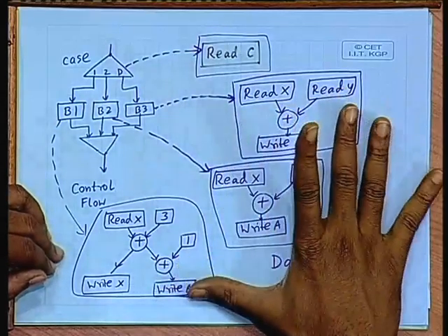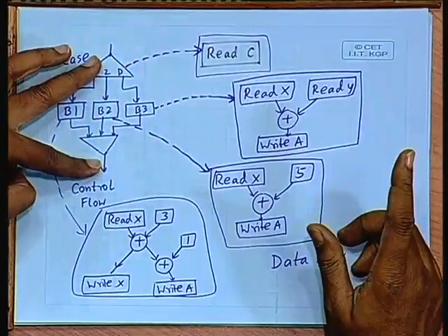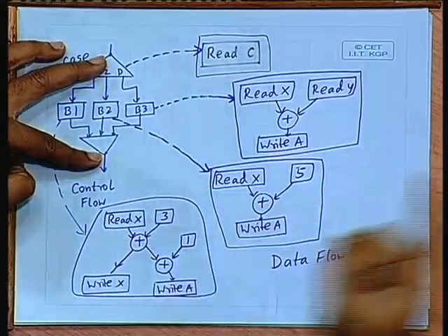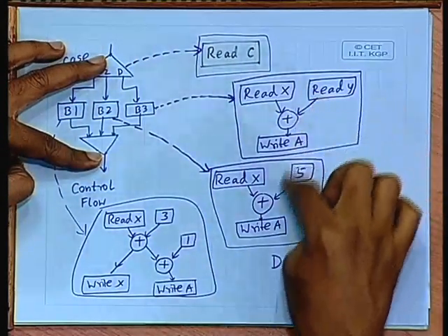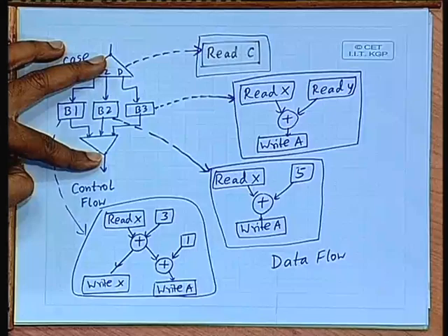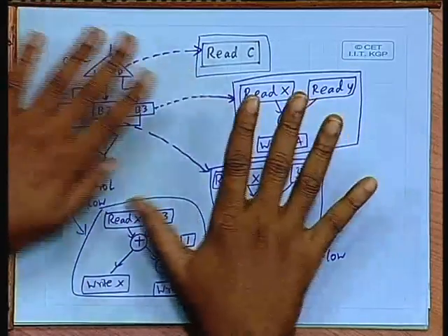That is the design of the data path. But once it is done, the control unit can be implemented as an FSM. The control unit will be simply generating the control signals to activate the data path, right. So, these two descriptions are generated concurrently so that they can be synthesized also together, right.